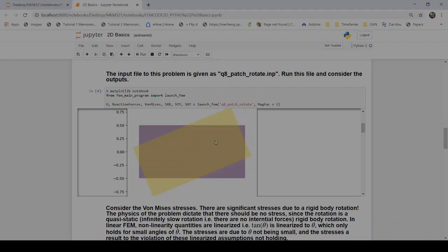Now we have a theory that we're building, linear elasticity, because we've linearized the angles, remember from the derivations of the shear strain. Also remember that we had that decomposition of the strain matrix into the skew component and the symmetrical component. We only used the symmetrical and threw the skew component away. That skew component is actually a rotational component. We claimed it's zero, so essentially we forced it to be zero.